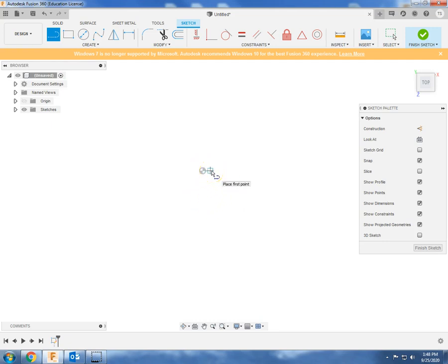So we're going to do what we're going to do. Let's draw a couple lines here. I'm not going to do a rectangle this time. I'm actually going to do a line. I'm using screen recording, so you won't be able to see the blueprint. I can't hold it up in front of you, but I'm looking at the blueprint and I'm going to go up. I'm just going to create two lines going up. Oh, keep it at 90. I don't care how long they are. And go across. Hit escape to get out of the line measurement.